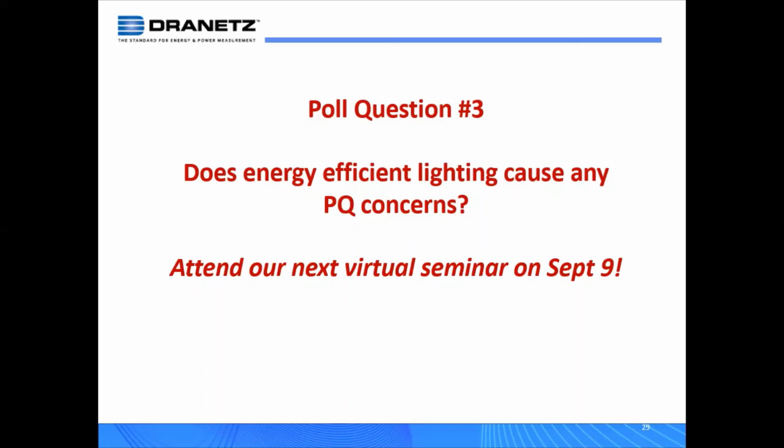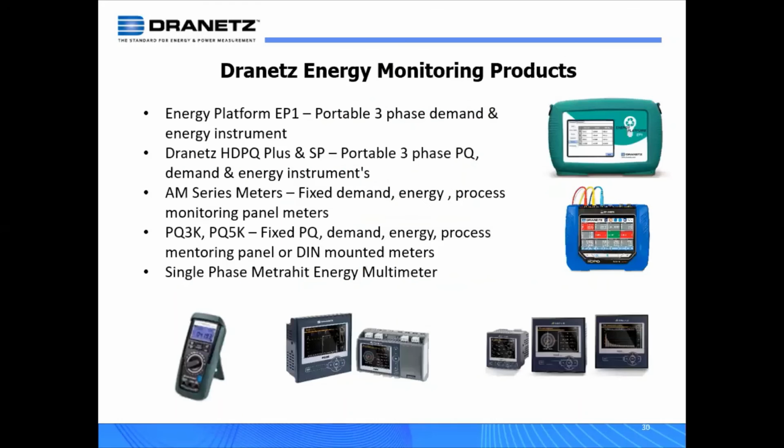But if you're not watching the power quality, you can have a single power quality event that can come along and basically delete any energy savings that you might have accumulated. So it's always a good idea, if the instrument is capable of providing power quality data, to always be monitoring the power quality as well. And we'll get more into the power quality aspects at our next virtual seminar on September 9th.